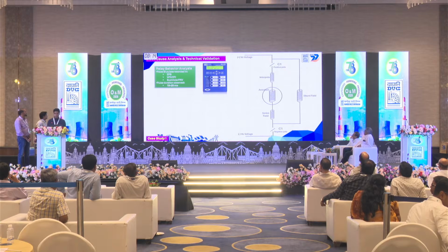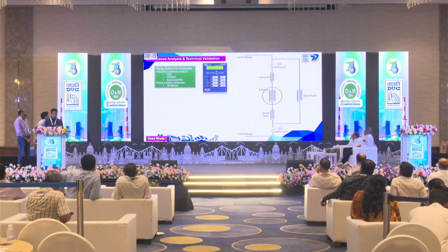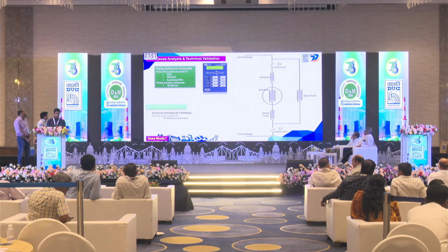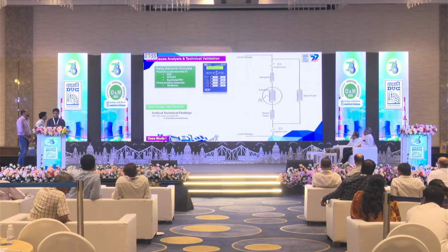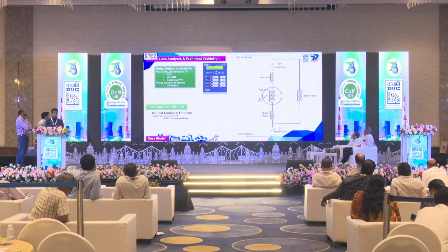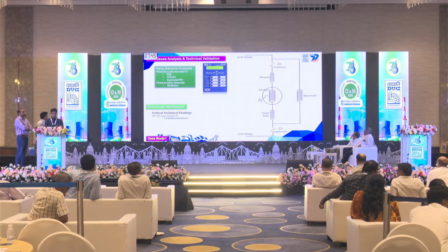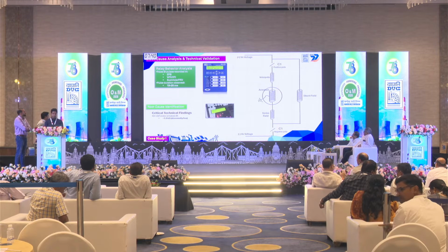During root cause analysis, we studied the relay DR, and we found the relay generated the trip command for the feeders because of false binary input pulses of the emergency push button and winding temperature indicator. But the pulse duration was very short, 18 to 25 milliseconds. After that, we also checked the motor. We found interpole, shunt field, series field, all IR values were okay, and motor parameters were absolutely okay, but its armature had a critically low IR value. We also checked the C1 contactor timing test, and it was in order.